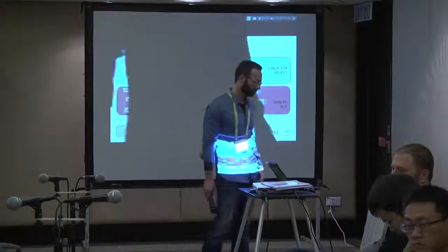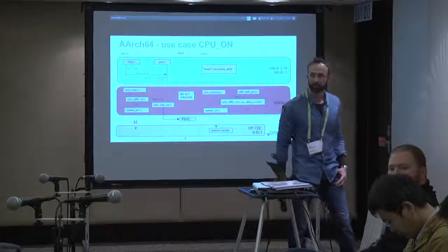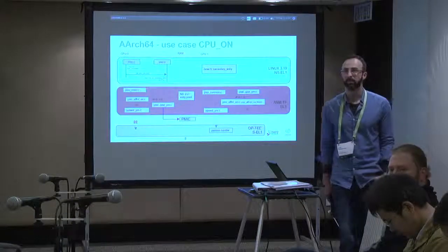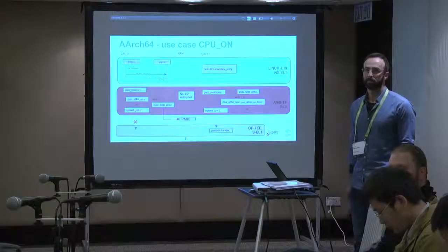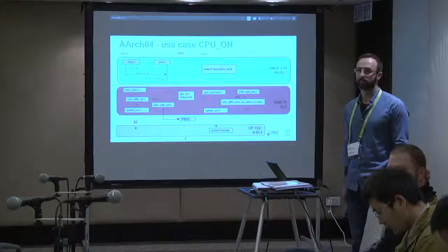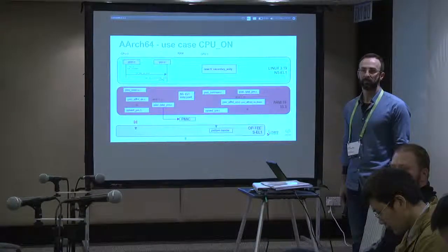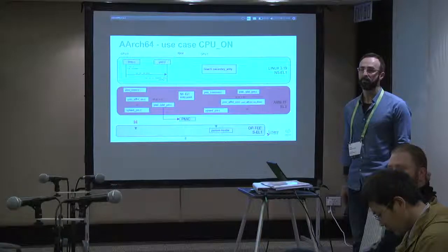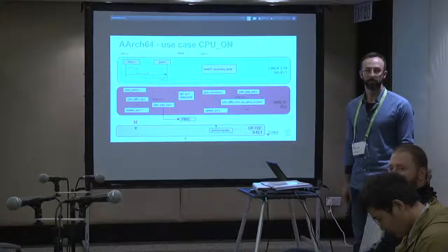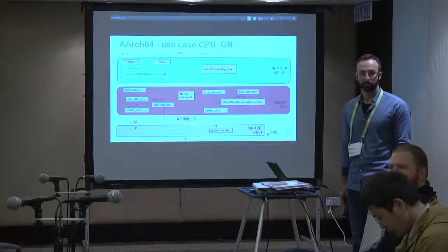Yeah, that's true. It'd be more logical to have the trusted firmware expose some interface that would allow Linux access to the bus if you wanted to do that. So provide a higher level I2C interface, which the trusted firmware could then audit. Have you planned to create a virtual I2C controller? Yeah. That's so that you can manage all the transactions.